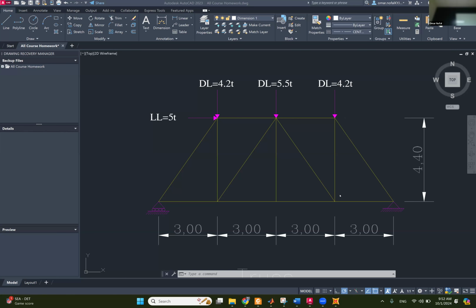Because if you are doing a structure analysis and your material is steel and you entered it as concrete, that's totally not right. Well, it depends. If this is a determinate structure, it's not going to matter. But if it's indeterminate, it's going to matter. Okay, all right. But let's model everything right. Let's not focus on determinate or indeterminate. If this is steel, I need to make it steel. If it's concrete or aluminum, I need to make it right.